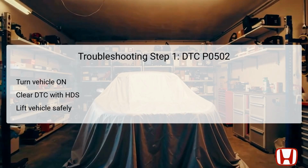In the first step of troubleshooting DTC P0502, the technician should first turn the vehicle ignition to the on position, enabling electrical systems without starting the engine. Following this, it's essential to clear the DTC using an HDS or Honda Diagnostic system, which can provide real-time data about the vehicle's health. Once cleared, the vehicle should be safely lifted on a ramp or lift, ensuring that all four wheels can rotate freely.